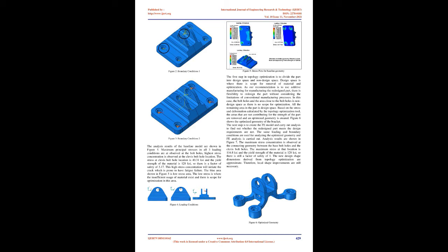Two common objectives of an optimization problem are to minimize compliance and volume. The compliance is the equivalent strain energy of the FE solution, which yields higher stiffness when minimized. Compliance is defined as in equation 7, where K is the global stiffness matrix, with K U equals F, and the elemental stiffness matrix uses the initial stiffness tensor.